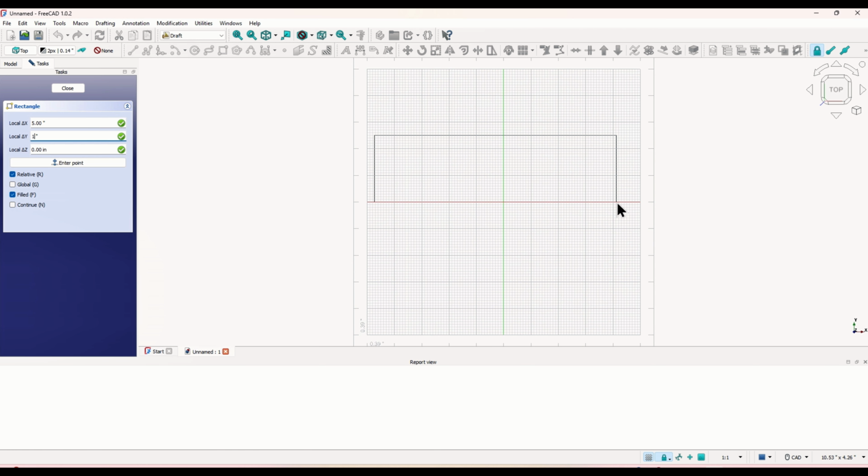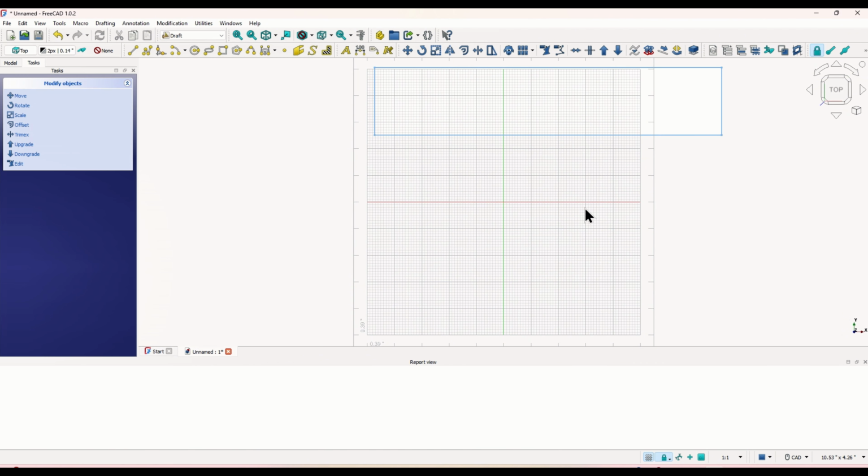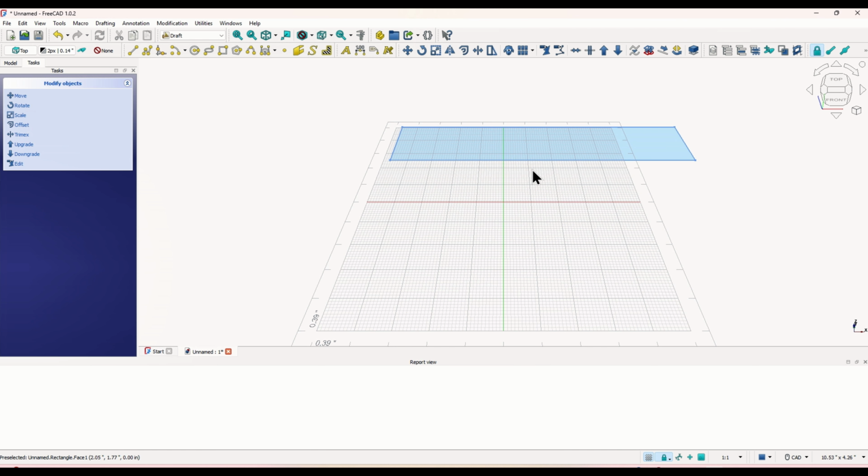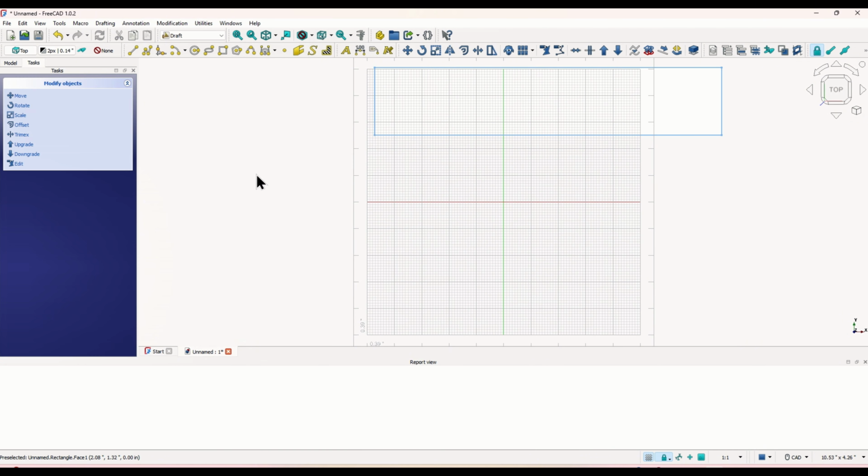And this being a 2D drawing, we're going to have a 0. See, that's exactly what I was talking about. We'll do it again here. So we're going to have 5 inches, 1 inch, and go ahead and enter your 0 and then hit enter. So that represents a 5-inch box with a 1-inch box from the top. And even if you rotate this, because we're in a 2D drawing, you don't see any change, because that's the way this works. It's simply 2 dimensions, X and Y.